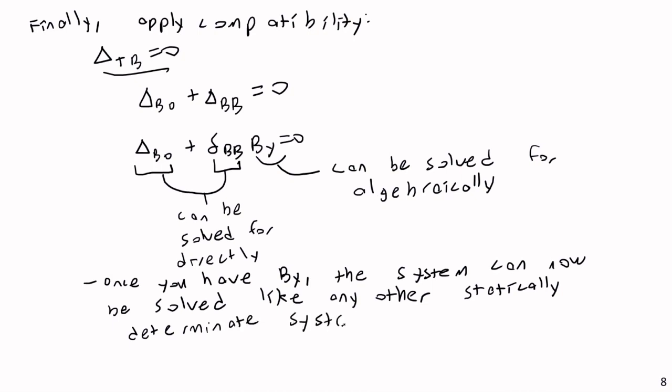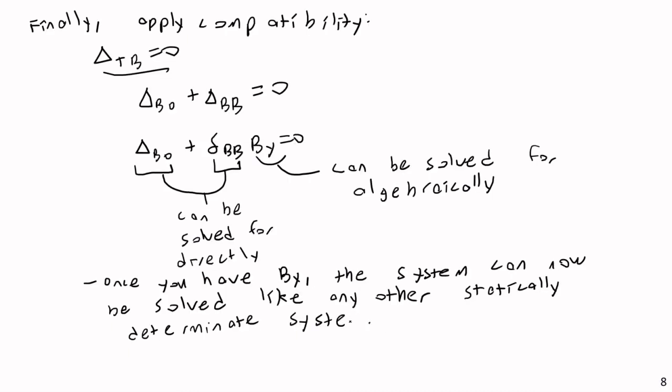What I mean by that is you're able to get, for example, your shear and bending moment diagrams, you can get your deflections, you can get your max moments, you can get whatever it is you want to get, whatever is required for your design. Once you have turned your indeterminate system into a determinate system, the rest is cake.